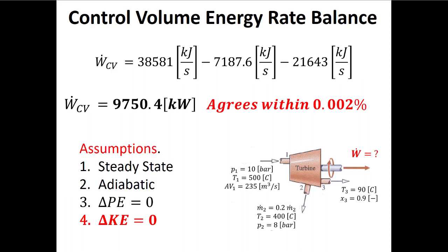On a jet engine, right at the front you have a diffuser, because you're trying to take the kinetic energy coming into the engine and turn that into more enthalpy. Then at the back of a jet engine, we're trying to maximize the velocity of the fluid coming out, so there we have a nozzle where we constrict the flow to maximize the velocity of the fluid coming out the back. But we'll get to that later on in the course.